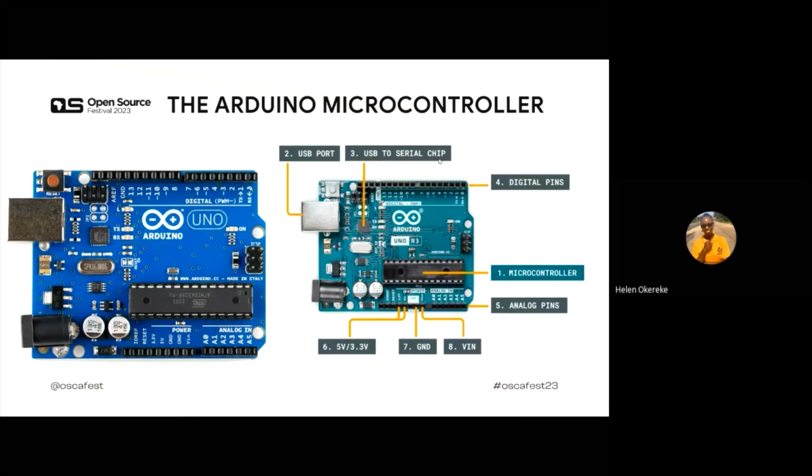So that we can be able to write values which are not 0 or 1 to that motor. Did you get that? If you connect that motor to pin 7, which is not PWM, we can't control that motor. We can't write to that motor, because when we are writing to the motor, we are writing the speed. We can say, let the speed be 25, let the speed be 100. So it's no longer 0 or 1.